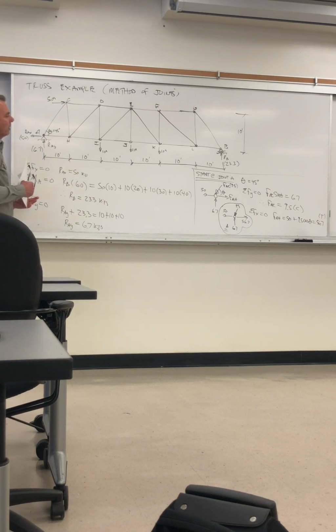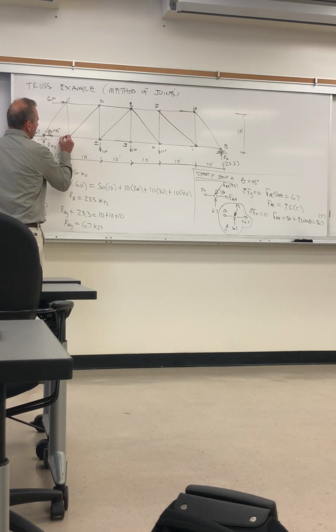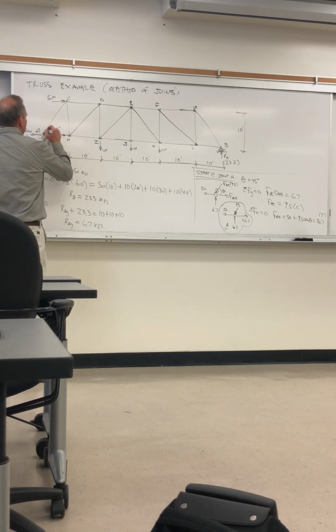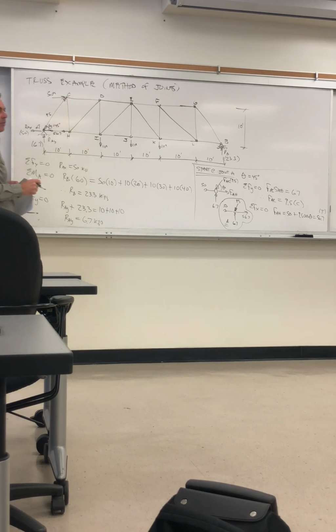So now, let's draw. We have 56.7 shown like this. I'm going to show 2 arrows. And then the other force is 9.5 here. I'm going to show arrows going out. That indicates the compression, okay? So if I'm drawing the arrows like I mentioned last time, I don't also put plus and minus for these guys. I just give them as positive numbers. The arrows tell me if it's compression or tension.